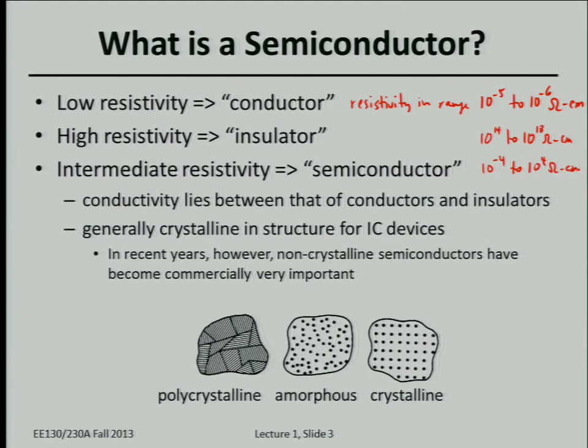But it's easier to put down a thin film of silicon if the atoms don't have to be lined up with each other. It's faster, cheaper. And for flat panel displays, it has to be really cheap. I mean, you don't want to pay more than, what, $100 for a display? So that means the fabrication process has to be really cheap. So you want to deposit really quickly and not worry about lining up one atom to another. You can get away with an amorphous material.